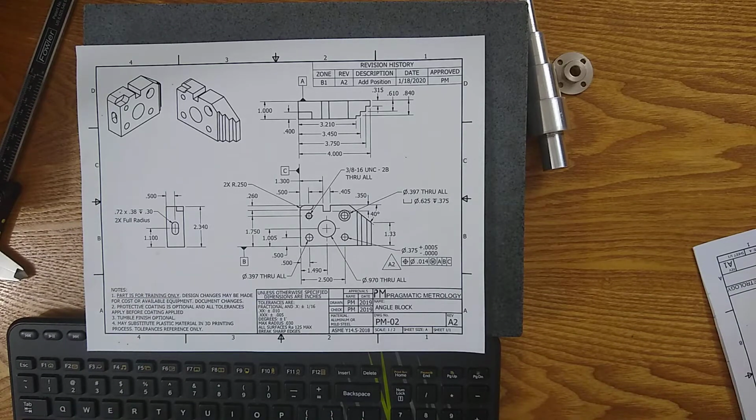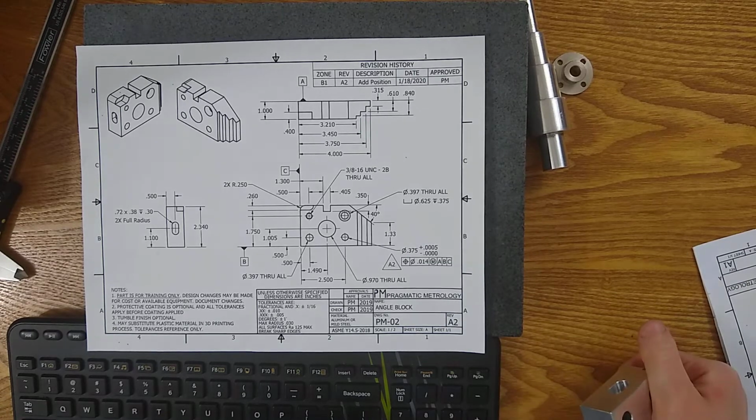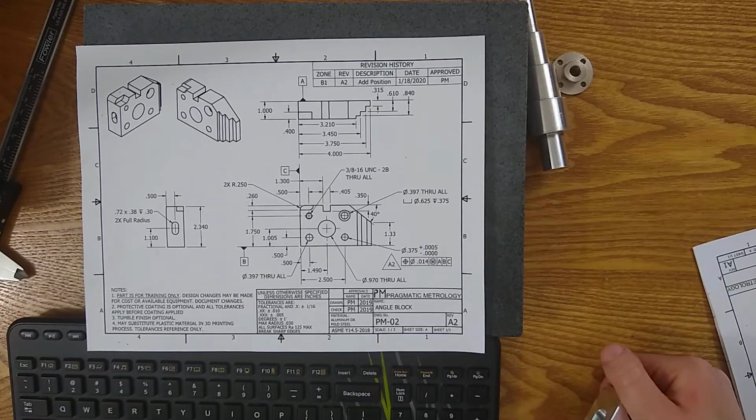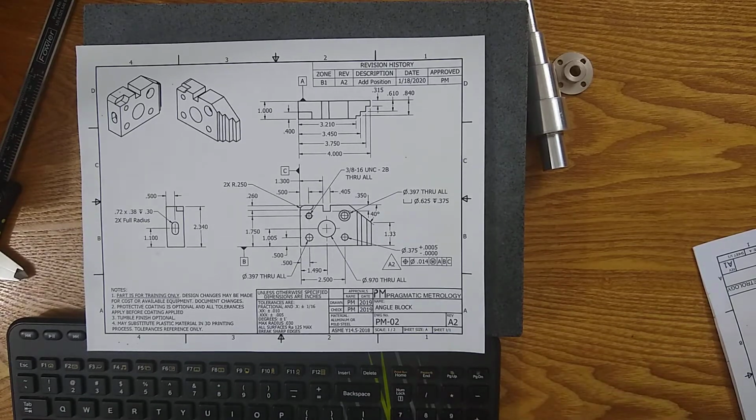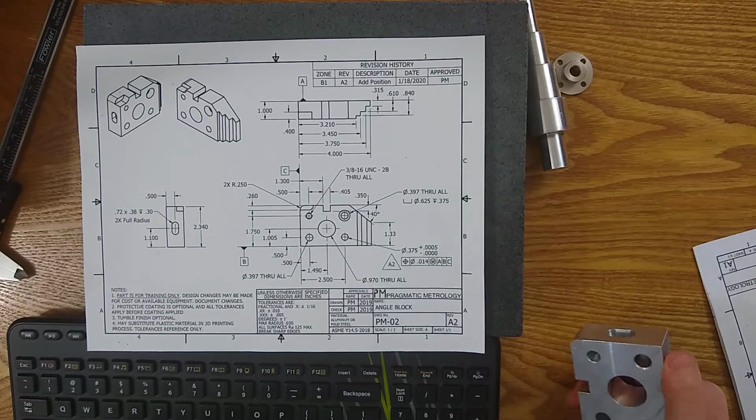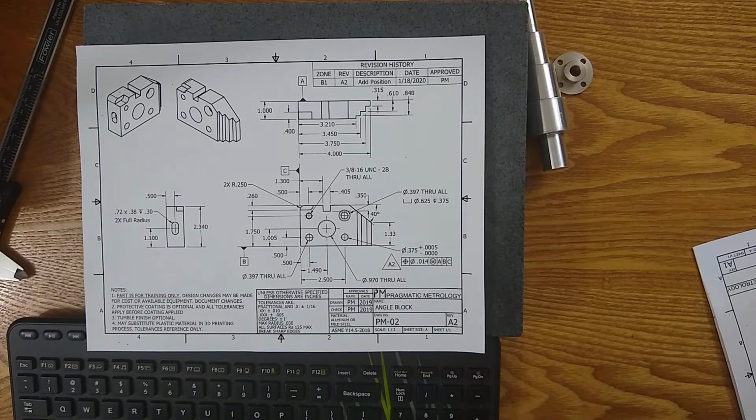Sometimes there's requirements on the angle at the bottom of the tip, whether it's going to be more aggressive or more shallow. But for the most part, you just don't want it to poke through. Depth only applies to the full diameter. So for this one, a blind hole, 0.375 down 1 inch. Well, like I mentioned, the tip, that triangular tip there, doesn't matter. We care about the full diameter going 1 inch, and we care about the tip not breaking through. That's how we decide it.